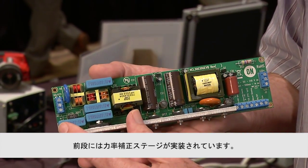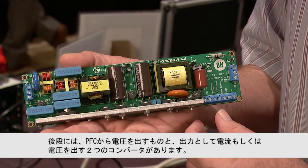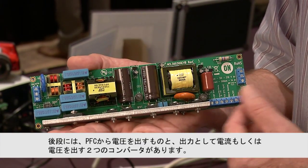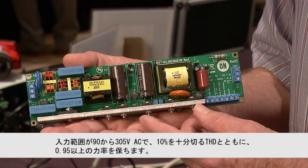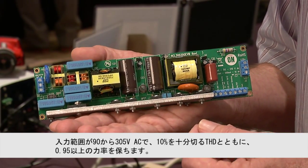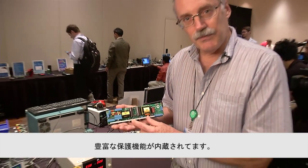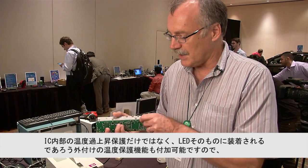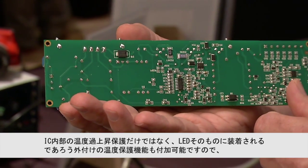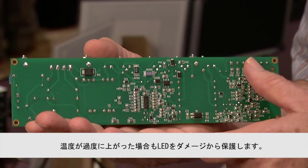We have the power factor corrector stage in the front end, and then on the back end we have a two-switch flyback converter that takes the voltage from the PFC and controls it down to either the current or the voltage controlled for the output. It has an input range of 90 to 305 volts AC, and it maintains power factor above 0.95 with a THD much below 10%. We have a lot of protection features built into this. Not only does the IC have an internal over temperature protection, but there can also be external temperature protection that you may be putting on the LED itself in case that overheated, so you don't damage your LEDs.